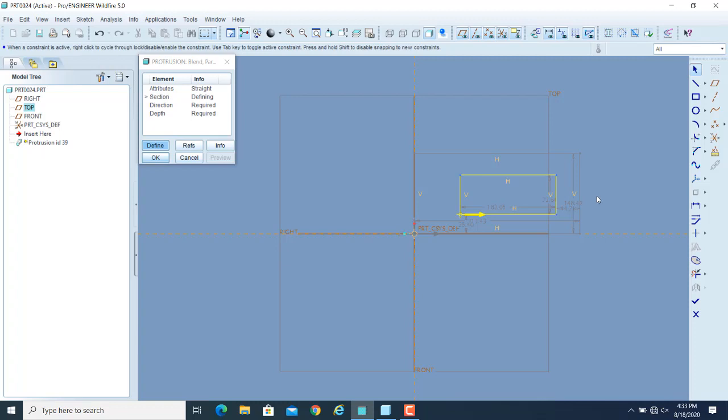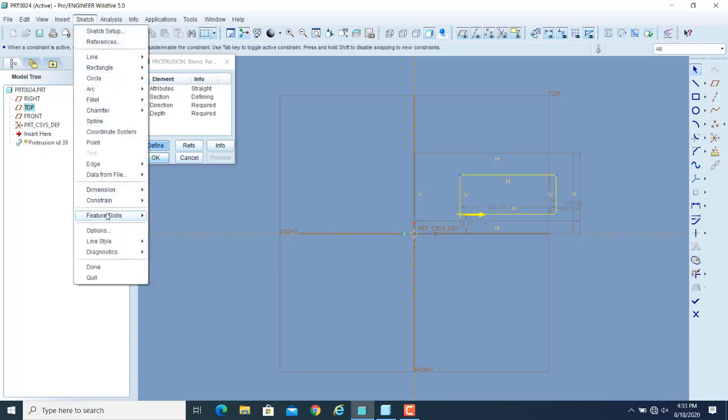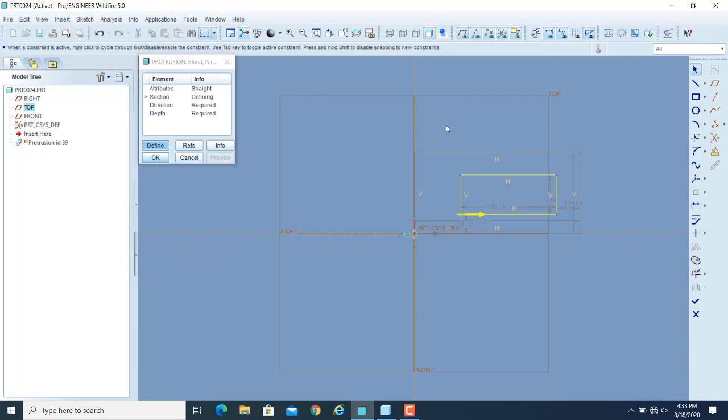So let me make another section also, so that you can easily understand that. So again, if you want to jump to the next section, you have to either use the sketch feature operations toggle, or simply right click and then you can click on the toggle section. And again, I will make another entity, for example, with some other dimensions. So again, this is the first point. So right now we will have straight edges in between those rather 3 points.